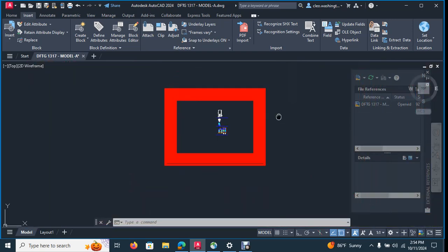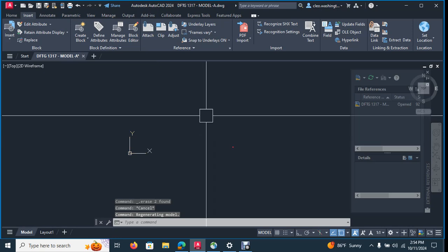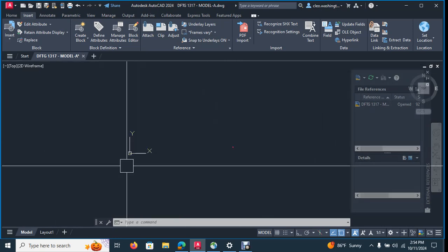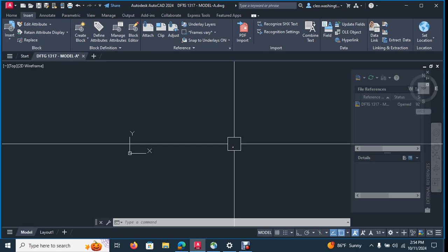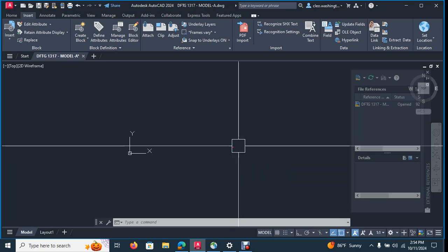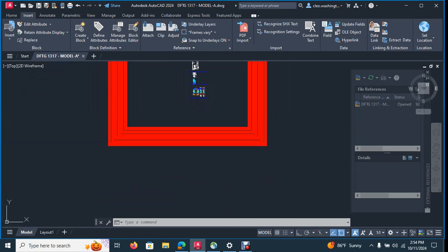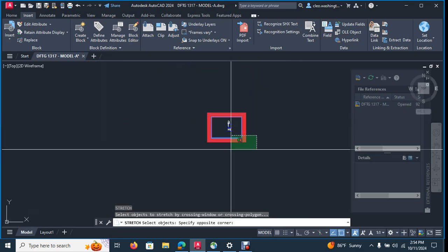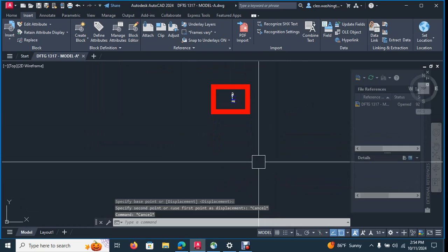All right, so now let's stretch out. If you have a bounding box, and I add that in because sometimes AutoCAD will zoom out like this. And as you can see, it's a very huge world space. And if I didn't have that red box drawn in the way I have it drawn in, it'd be very hard to locate your drawings. So I actually draw a big red box, a bunch of polylines, and I give them thicknesses. And I just kind of do that as a reference point. So let's stretch this out because we're outgrowing it. So just turn your function back on, function F8.